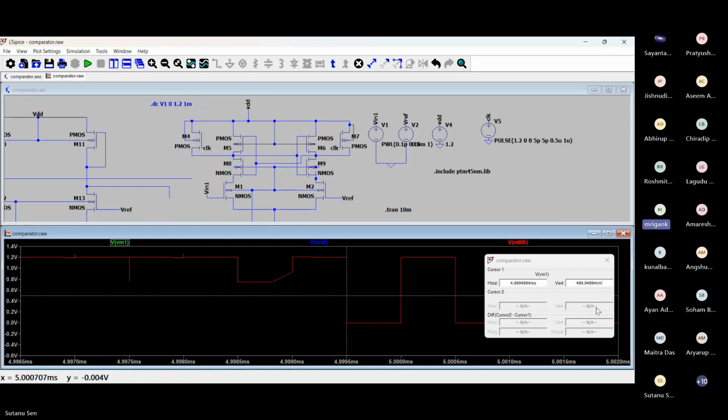Yes, you have to see whatever is the smallest difference for which it is able to switch, right? So here, the moment it crossed below the 0.5 volt margin, it is going to flip here. So what is the smallest difference for which it is flipping? Here, even for 0.05 millivolt, the moment it has gone by even 0.05, it is switching in the right direction. So that shows that it is able to detect the 0.05 millivolt difference correctly at this clock speed.